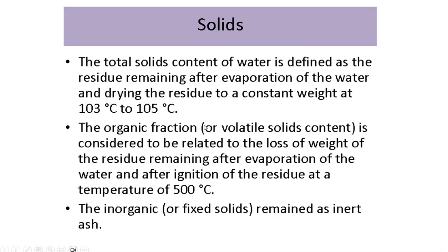Then we have solids. Solids in the water are defined as the residue remaining after evaporating the water and drying the residue to a constant weight at 103 to 105 degrees centigrade. The organic fraction, the volatile solids, is considered to be related to the loss of weight of the residue remaining after evaporation of the water and after ignition of the residue at a temperature of 500 degrees centigrade. The inorganic fractions are fixed solids that remain as inert residue.